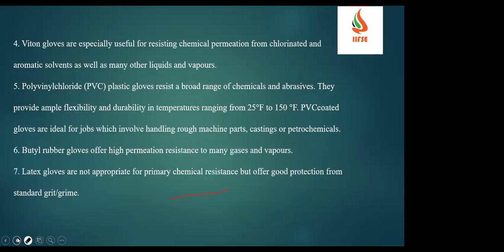Then Viton gloves, especially for resisting chemical penetration. And PVC, this is also plastic gloves resistant to a broad range of chemicals. PVC, I can say this is a well suitable glove for most of the chemicals. Many of the chemicals can be handled by using these PVC gloves. Then butyl rubber, this is also one of the gloves which is used to handle chemicals. Latex also, latex we can say surgical gloves or disposable gloves, which is also a chemical handling glove, I can say.